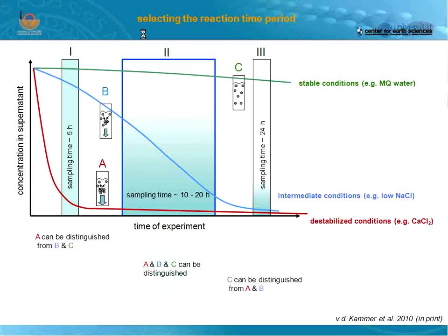So we have an 815 nanometer IR diode pointing into our vial, and we are measuring the stray light or the scattered light at a 90-degree angle from that. And that works, as we all know. It has some drawbacks because the particle size and the refractive index are also a factor in the signal here. When you have a higher refractive index, then you get a higher scattering signal. So you would probably get some errors here. But we're only working on the titanium dioxide here. We are doing a calibration curve, and we are working in highly polydispersed samples.